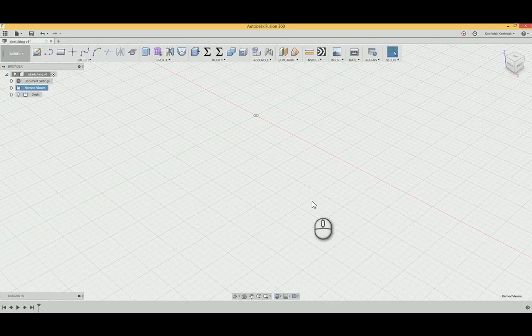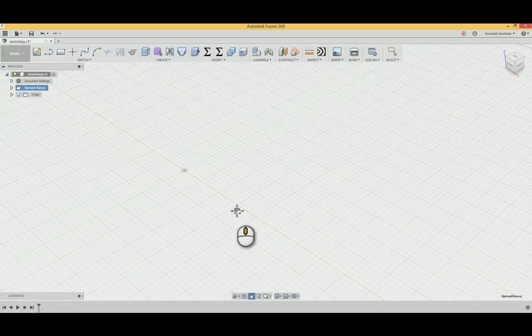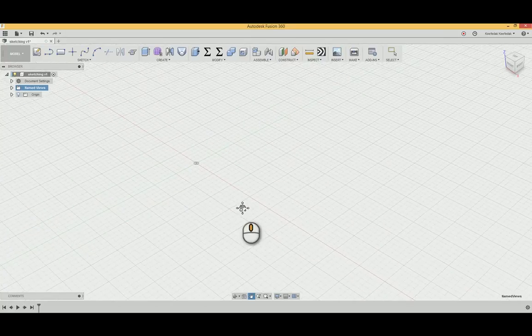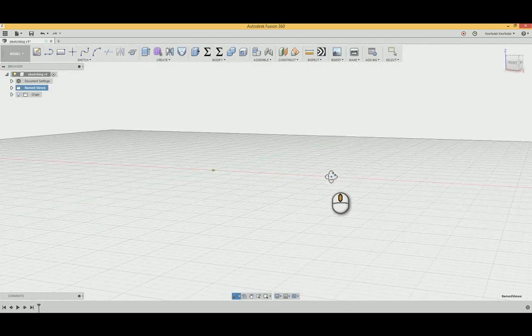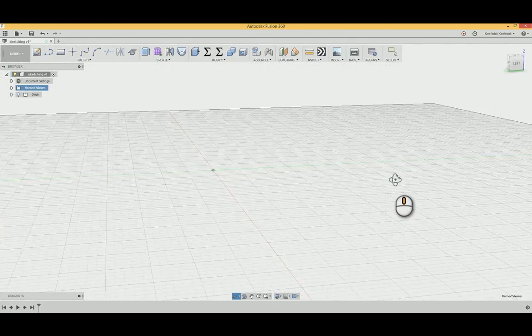The next thing with the mouse, you probably hardly ever use it, but you know how you can click it, right? You click and hold it, and you can pan your screen side to side and up and down. The other thing that you can do, if you want to orbit around an object, you hold the Shift key down, and then you click and hold the wheel, and you can pivot the plane and pivot around your object.